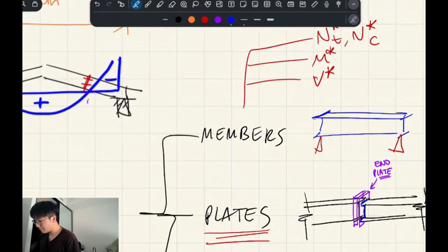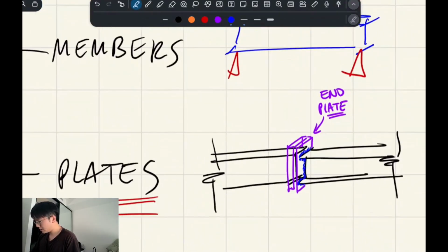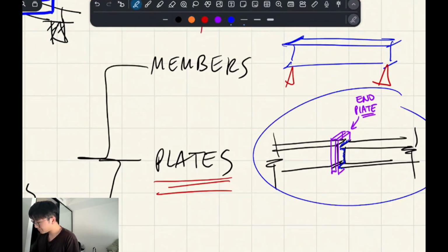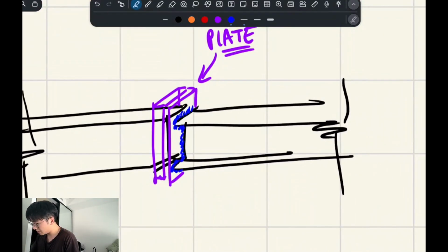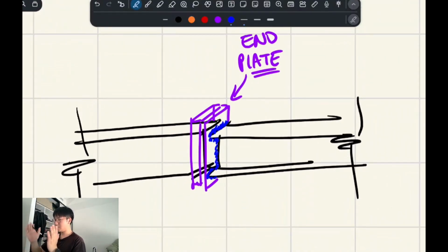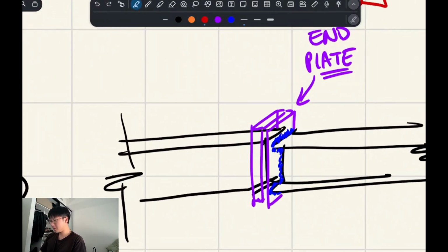What I was trying to say is we've got these end plates, and you do this continuous fillet weld to attach the plate to the beam, and then to attach the plates to each other on site, you would install these bolts such that they connect through to the other side, across like that. And you stitch these together.